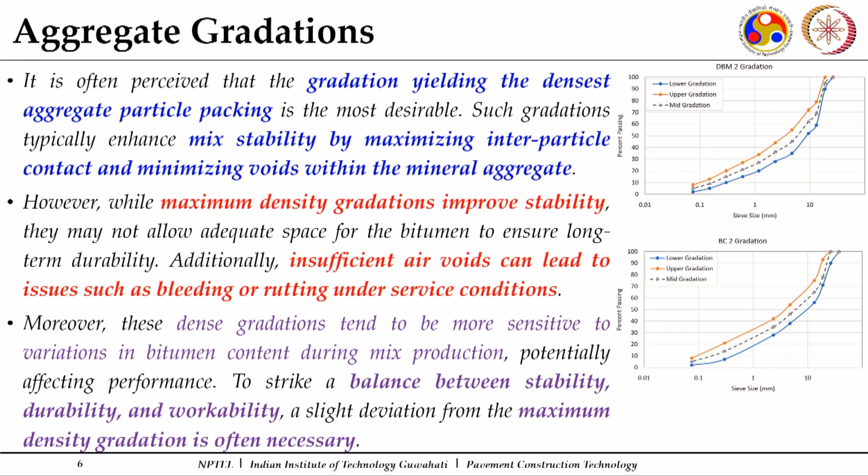So, first, aggregate gradation. As in the case of granular courses, here aggregate gradation is very important. As I mentioned, the general conception is that if I have the gradation yielding the densest aggregate packing, it will be the most desirable one. Why is this conception there? Because such gradations typically enhance mix stability by maximizing interparticle contact. When particles come close together, their interparticle contact is more and their load transfer is better, while voids within the mineral aggregates are minimized. So, this is a normal conception.